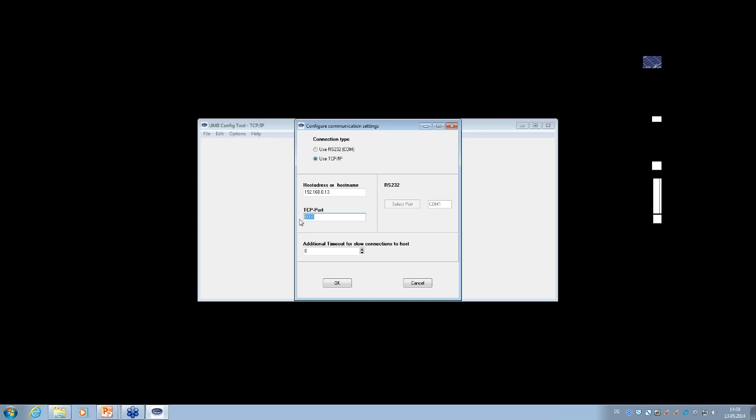So I will try that now live. I have a station nearby my office. It's about 50 kilometers away, and it's a RWIS station, a road weather station. So we will try to connect. So what I need to do is to enter the IP address. Because the station is a GPRS modem station, I need to use the right port, which is 2404.